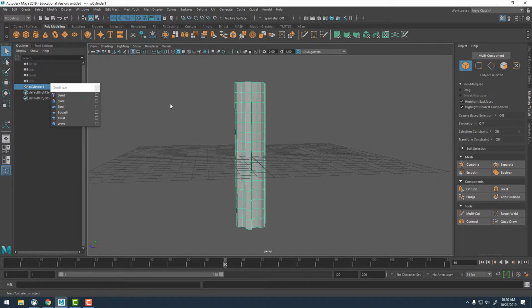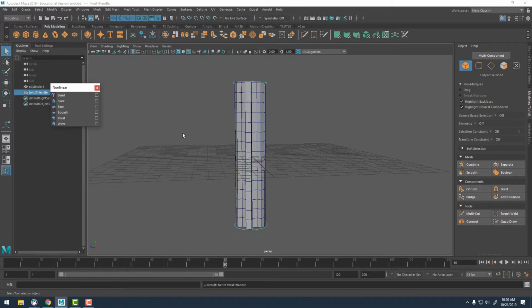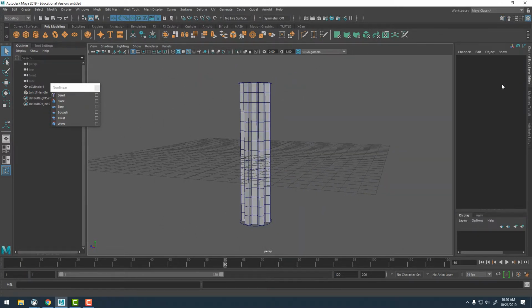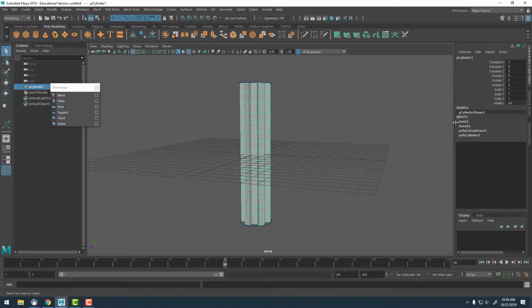And then let's grab this shape and I'm going to turn on the wireframe and then I'm going to add the twist deformer here. And let's go into the twist deformer's options. So I'm going to grab the geometry, open up the twist, and this has a start angle, end angle, low bound, and high bound. So with this one, our primary controls are coming from the start angle and end angle, and really this just dictates where the twisting is happening from.